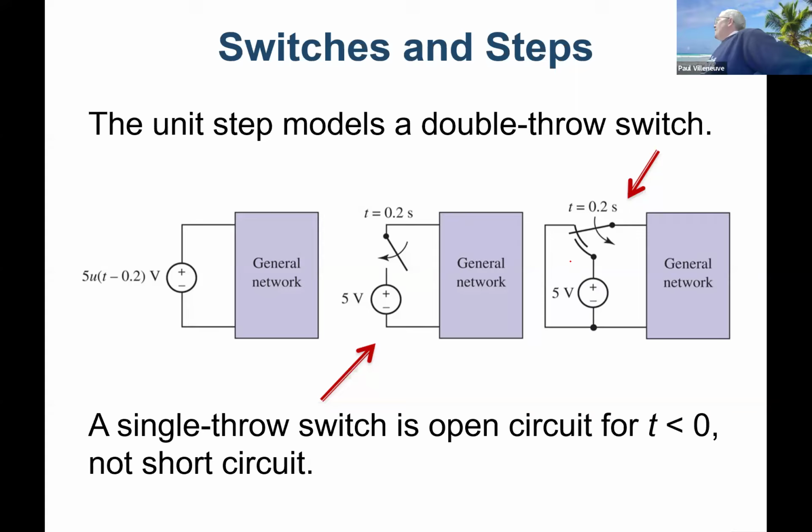So the first case, it's break before make, right? So you have to open it up before you transition. Over here, I'm connected. The circuit is always grounded, forcing it at 0 volts. And then I actually connect it to the 5-volt source. And then at that point, I open the circuit, okay? So that is a double throw configuration where you have to do a make before break type configuration. The reason why is that this is an open circuit, right? So your network is not discharging. This over here is actually not showing that that's at 0 volts, right?